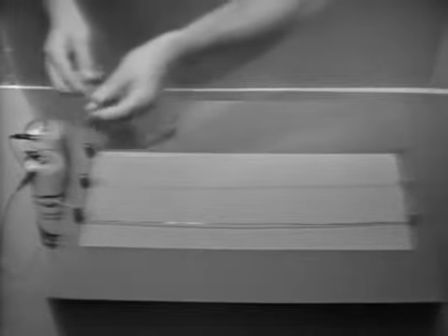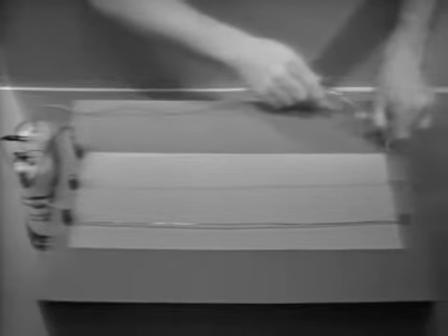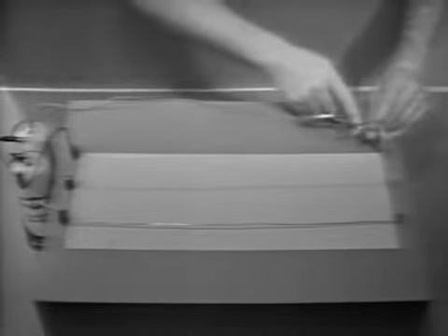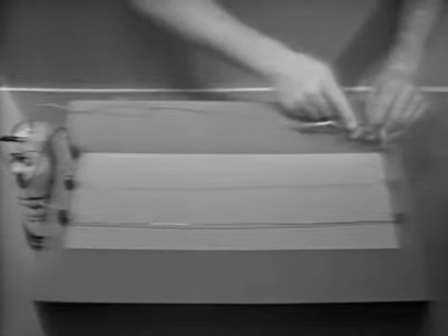Before we begin, let's check the intensity of the bulb with just the resistance of the bulb opposing the current from the battery. As you can see, the bulb is lit very bright. Now, in the first example, we'll use the small wire, and we'll see the factor length and how it affects resistance. Now, with the connection here and here, the battery must force current through the resistance of the bulb plus the resistance of this wire. There's very little current through the bulb.